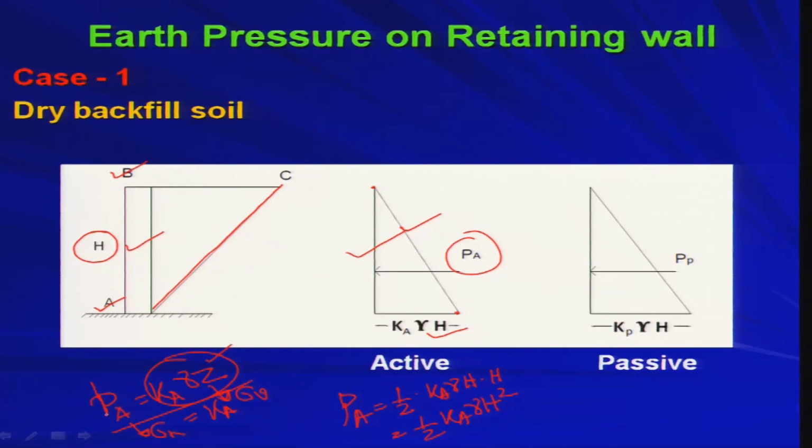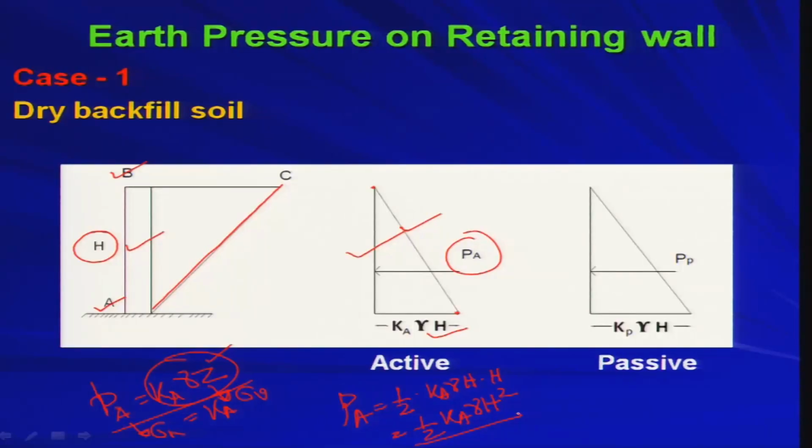Once I calculate this, that is the total force acting on the wall, and your wall should be designed based on this total force. You may think that as the pressure distribution is not uniform, but linear, you will have less section at the top if you think of the reinforced concrete design aspect. So you will consider less thickness at the top and higher thickness at the bottom, because maximum pressure has to be resisted at the base. These things give you the idea of how you can design your retaining wall.